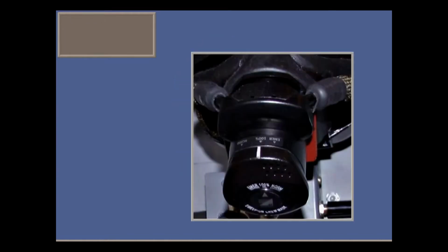The automatic diluter demand regulator supplies oxygen on demand and is controlled by this ring. It has 3 positions. Norm. The regulator supplies an air-oxygen mix which varies with cabin altitude. 100%. The regulator supplies 100% oxygen regardless of cabin altitude. Emergency. The regulator supplies 100% oxygen at a slight positive pressure.